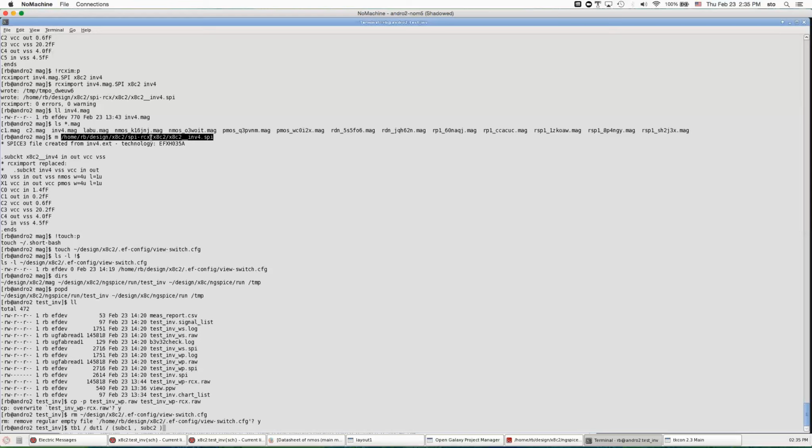And when I have an RCX extracted SPICE netlist with all these added passives, do you think ngspice in its current state can handle such a dynamic and diverse matrix of instances to begin with? Like if I'm supposed to run DC analysis or AC analysis, do you think it's a good idea?